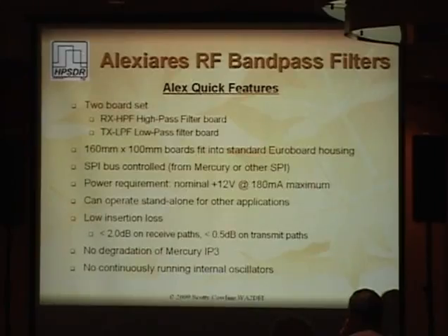Graham has actually designed up a little PIC board with an LCD on it, which allows you to use buttons, and you can cycle through the different bands in a standalone mode without having anything connected to it to control it. And one of the reasons they used big inductors was no degradation of IP3. I know Phil tried really hard to make this small and use smaller inductors. He wanted to use solid-state switching of the filters.